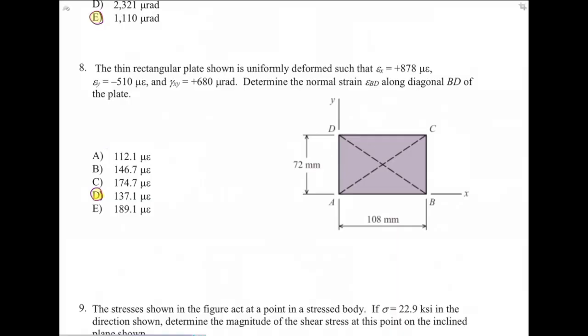Simply, it asks you to rotate the strain and determine how much is the strain in that angle. So we need to see what is theta and what equation should we use. Okay? Here, again, there are two ways to solve this problem. Here I assume that I'm starting from the right surface, and then I rotate that like this to that plane. Okay? Here, again, the theta is counterclockwise, so that would be positive. How much is that theta? It is not given, but we can determine that.